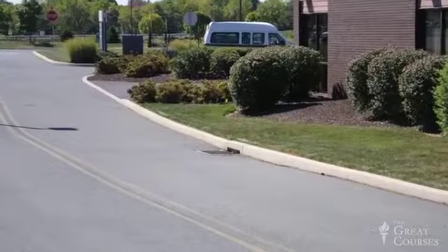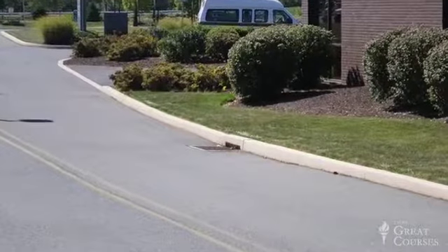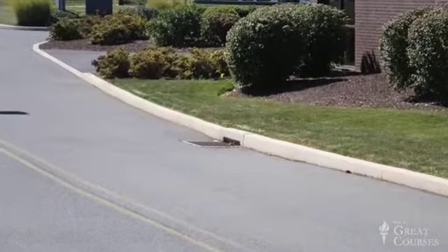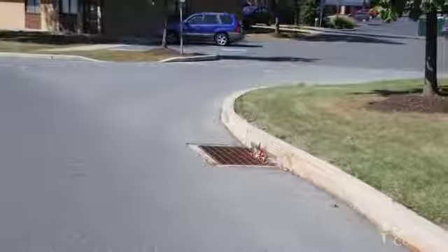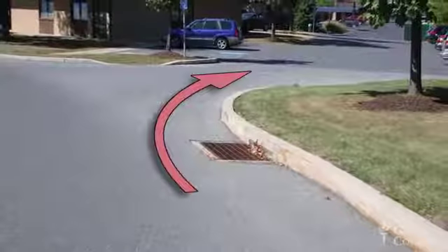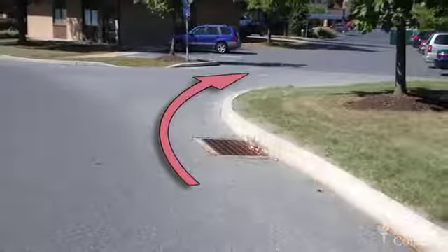Now, in designing this system, we would first determine appropriate locations for the inlet structures. These are placed at a minimum at low points in the road network to prevent water from pooling here, and immediately uphill of intersections so that storm runoff doesn't create a safety hazard by flowing across the intersection.